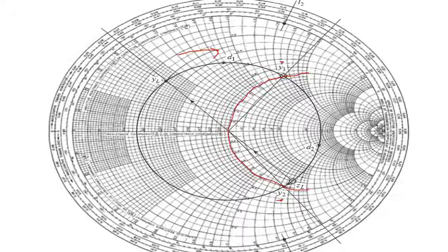So how do we find it? You are supposed to draw a straight line passing through the point Y1. Can you see over here? This line is already drawn. A straight line passing through the point, and this line has to be taken outside the Smith chart because whatever answers you're going to tell us are always going to be in terms of lambda. If you remember, the entire circumference of the Smith chart was 0.5 lambda.